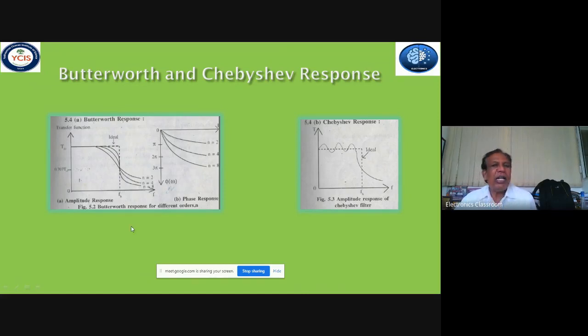So it should be written as a gain decrease: for a 10 times change in frequency, the decrease of gain should be 20 decibel per decade. That means 20 decibel per decade represents a decrease in the gain. When the frequency increases 10 times, say from 10 kilohertz to 100 kilohertz, the gain decreases by 20 decibel, so that unit is known as 20 decibel per decade.